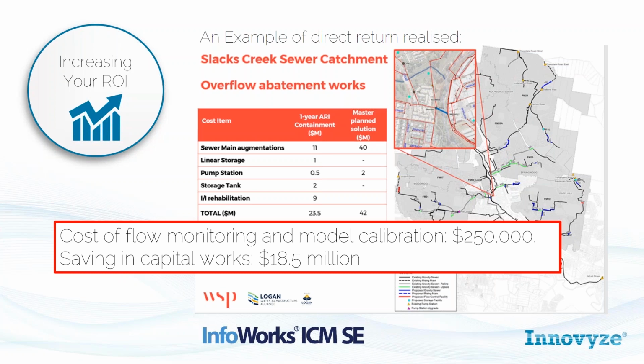So there's parallel mains running either side of the creek. The peak flows on the west side of the creek move quite a bit more quickly through the catchment than the peak flows on the east side of the creek. So in lieu of building a large diameter, high cost parallel duplication on the western side of the creek, we actually just, I believe the construction of this is recently finished, put a cross connection in across the creek at a significantly reduced cost to take advantage of the spare capacity in the main on the eastern side of the creek. It's a spare capacity that's there in time. If you were to do a steady state static analysis of this network, you wouldn't have discovered that.